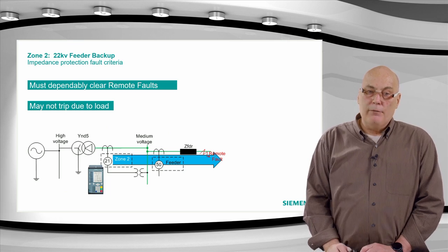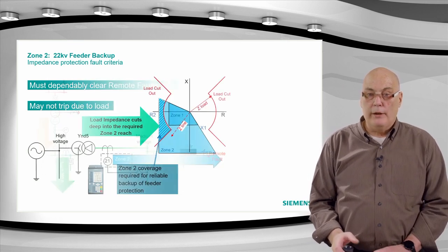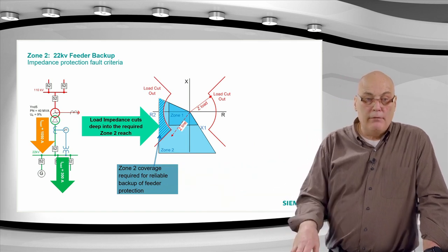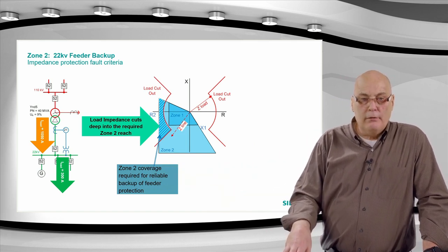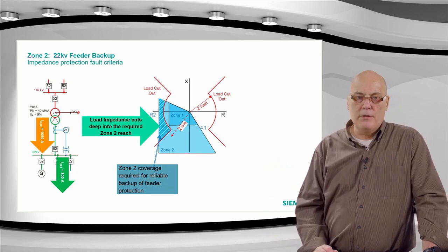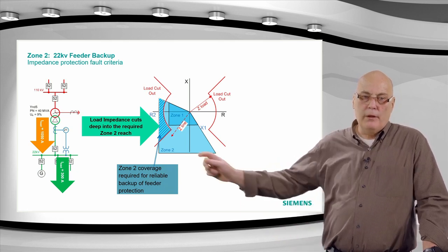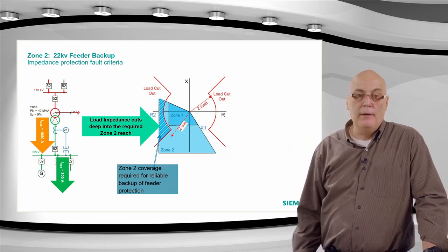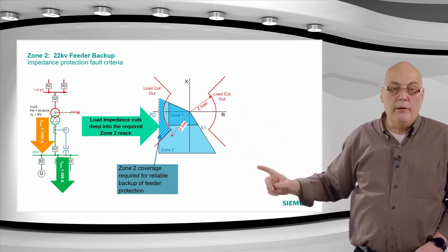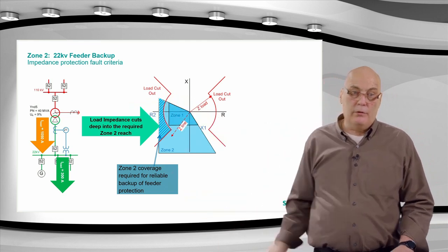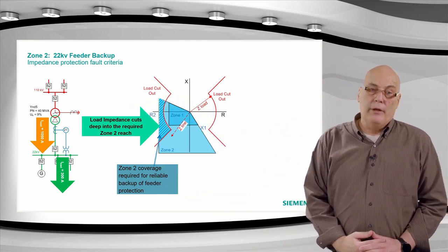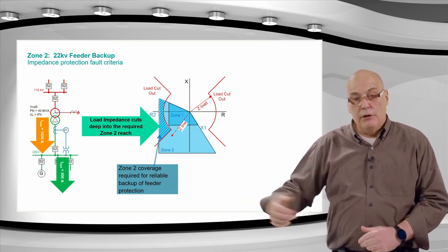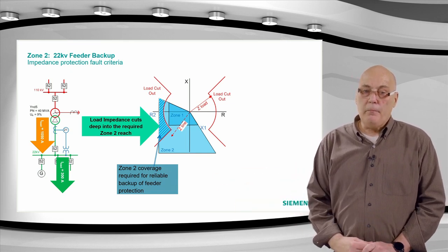All right, and that is difficult because we have a coordination of load and fault in-feed. You can see here at the bottom, the feeder might have a 300 amp load current, and the according setting may be set to 400 amps to coordinate with the load, tripping at 400 amps down there. And the load current on the transformer is all the feeders in parallel. If you have a 40 MVA, I can now see I've gone up to 40 MVA with the transformer, but that's typically what's happening. You get 1000 amps full load current, all the feeders in parallel, but each individual feeder only 300 amps. And you have to get a pickup.